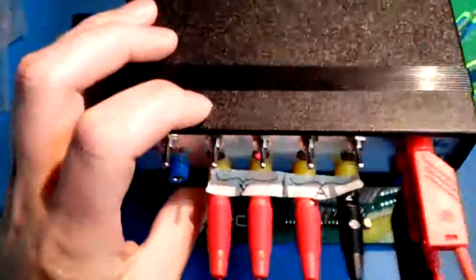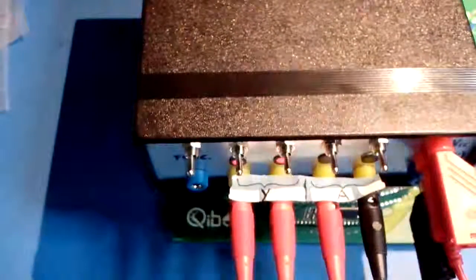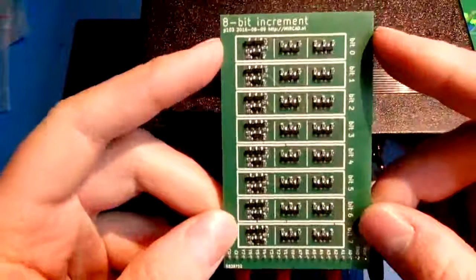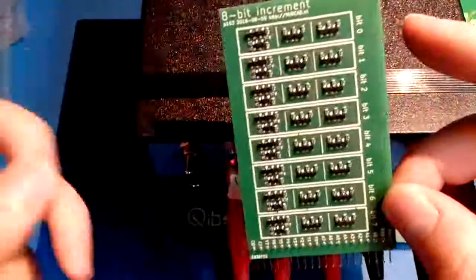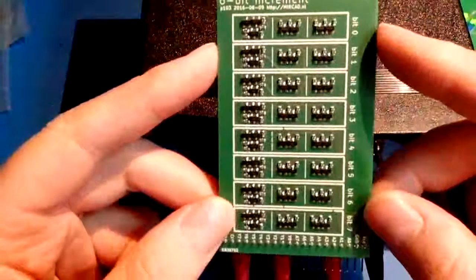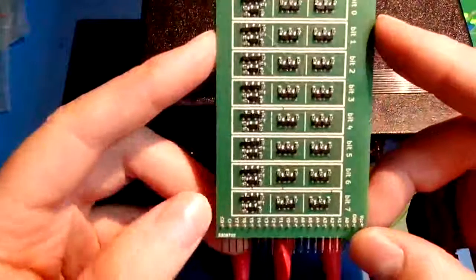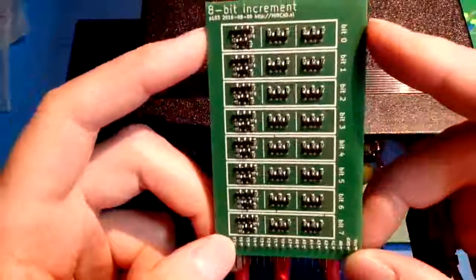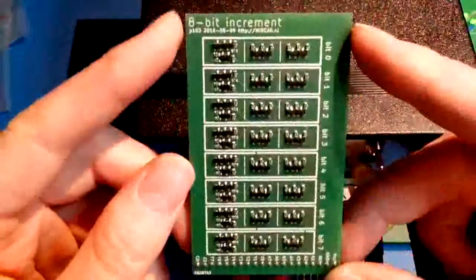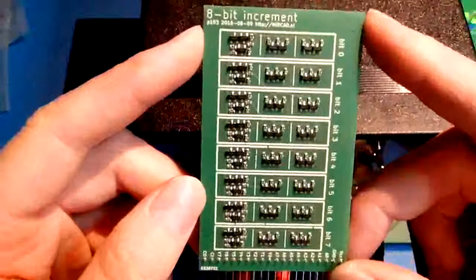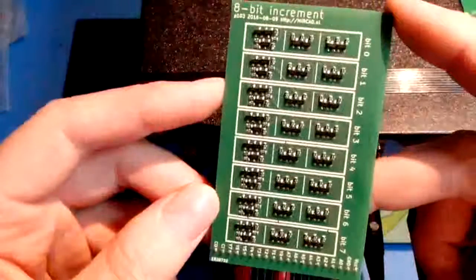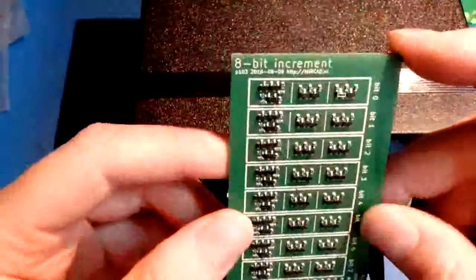When cascading this module, because there are 2 of these modules in the CPU, the carry in of the first module will be made 1, because we're adding a constant 1 to whatever comes in, and the carry out of the first module in the chain is connected to the carry in of the second module in the chain, and the carry out of the second module is simply discarded because there are only 2 modules in the CPU. So what these do together is add a constant 1 to a 16-bit number, which conveniently is the program counter. So that's how it works basically.